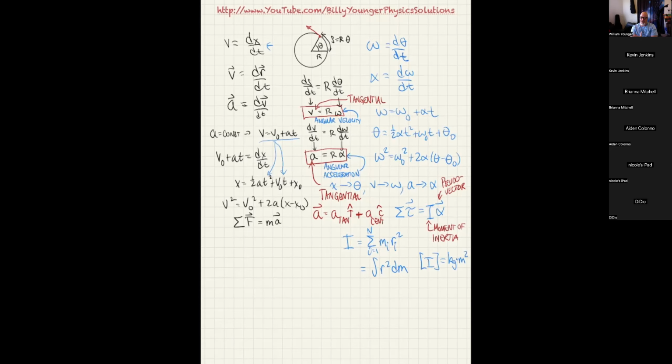So if you try to pull out the mass part of that, that means more or less you're going to try to be dividing out the density, which relates mass to volume. And that can sort of make you see that, oh, if I divide R squared dm by the mass per unit volume, that's going to give you inches to the fifth power. So you can at least sort of see why the units are different, even though it's an entirely different quantity. It is related to it. It's just a weird way that you have to deal with. The good news is it's actually pretty clear once you start doing it in statics.